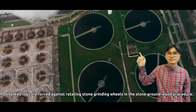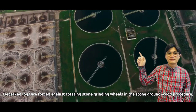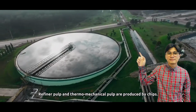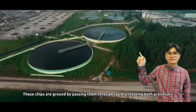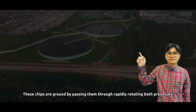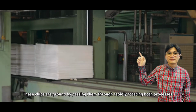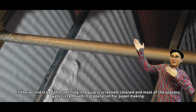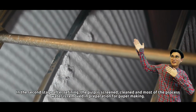Debarked logs are forced against rotating stone grinding wheels in the stone groundwood procedure. Refiner pulp and thermomechanical pulp are produced from chips. These chips are ground by passing them through rapidly rotating discs in both processes. In the second stage of refining, the pulp is screened, cleaned, and most of the process water is removed in preparation for papermaking.